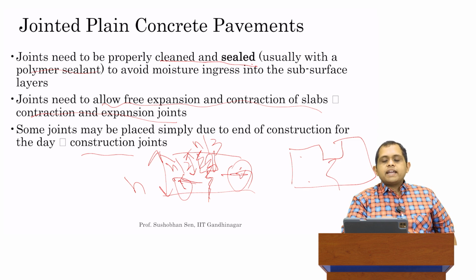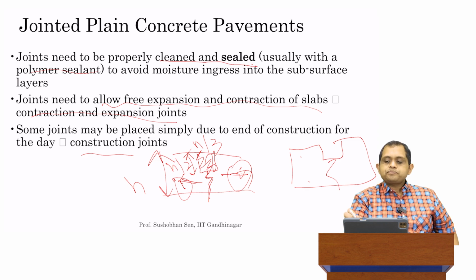It is very important, again, that joints have to be properly cleaned and sealed to prevent any moisture ingress from coming in. Otherwise, the entire pavement can be damaged in a relatively short period of time.